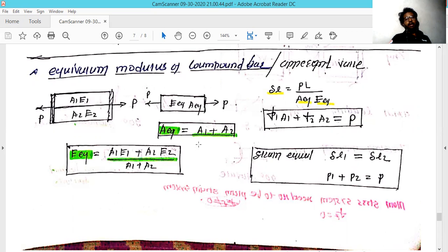In this cross section, you can take that the total change in length for both materials is going to be the same, because it is fixed on both end sides. You can see the hash lines on both ends. The two ends are fixed to each other, so they are not allowed to deform in a different fashion; they deform in the same fashion at the end.